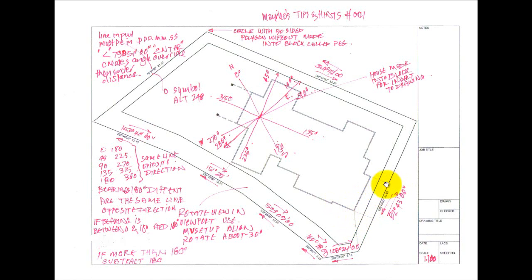Now it showed another offset from here to here in this area, so I put that offset line in, and then I rotated the house about this point, using the reference line. I clicked on here, and then dragged the reference line to meet the offset line that I'd drawn, and then I rotated the house accordingly, clicked it all in, got rid of the offset line, and then checked that these measurements agreed with what was on the original site plan, and yes, they did.